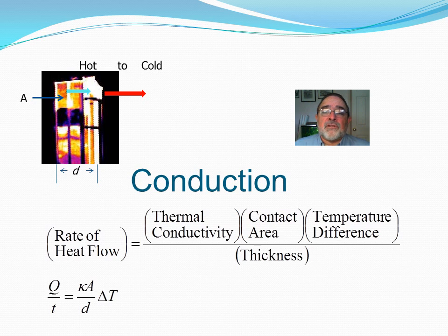That rate is the thermal conductivity of the mass multiplied by the contact area if we were conducting from one mass to another, as is frequently the case, and actually is here, since this is a box made out of 316L stainless steel. You can see the hot edge, let's say right in the center or at the top and on the left. Those are edges or corners. There are other ones here, but those are edges or corners you can see, where actual conduction is taking place.